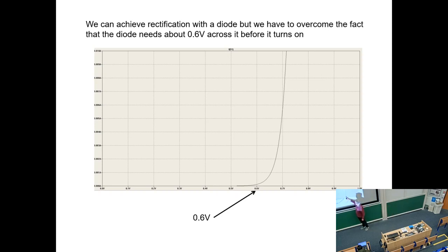So this is why people say that about 0.6 of a volt is the turn-on voltage for a diode, because below that, it might be doing its exponential thing, but you can't see it. Above that, it happens really quickly. So 0.6, 0.7, depending on who you talk to and what's the chemistry of your diode. That's when it comes on. But what it means is that any signal that's occurring in this region, below about 0.6, the diode isn't really going to respond to.